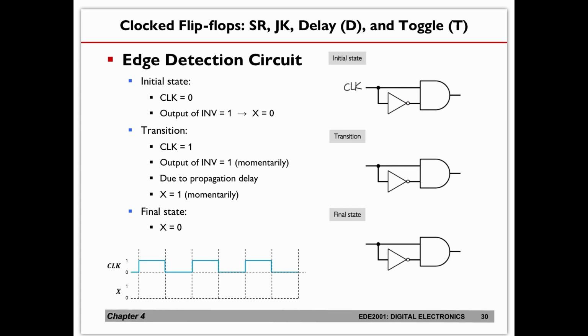On the surface, it seems that the output of this AND gate will never be a 1, because the inputs here and here will always be opposite. But let's take a little while to think about how these gates work. Inside these gates are actually transistors, which require some time to process the signal, maybe a matter of microseconds.